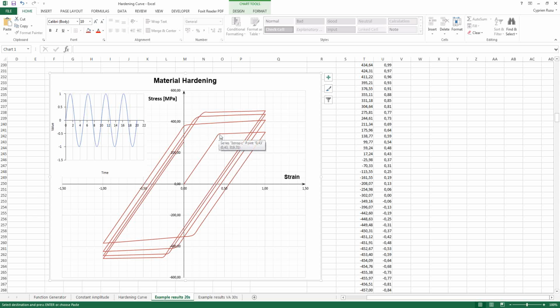the plastic limit is exactly the same for the loading condition and unloading condition. So those values are pretty much the same. So this is 320 almost, let's say, and in the opposite area is almost the same. But so 320, it depends on the resolution of my graph. So this is isotropic, and of course we are observing that the material is hardened.